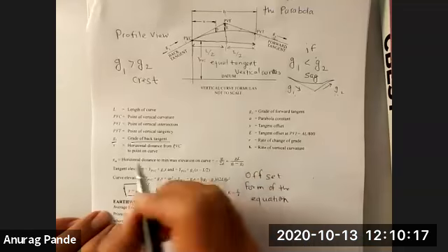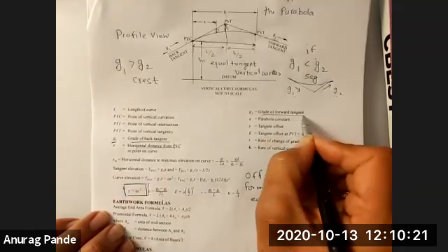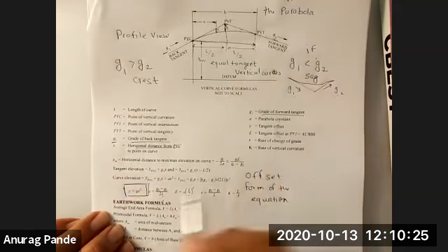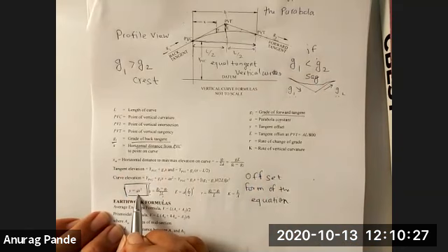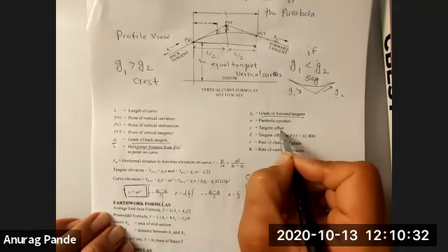E is equal to... so let's look at x, the horizontal distance. g2 is the grade of the forward tangent, basically the end tangent. A is the parabola constant. I told you already how that's defined: small a is g2 minus g1 over 2L. Y is equal to the tangent offset.